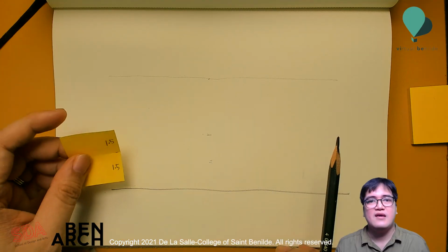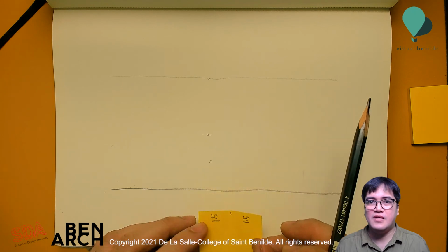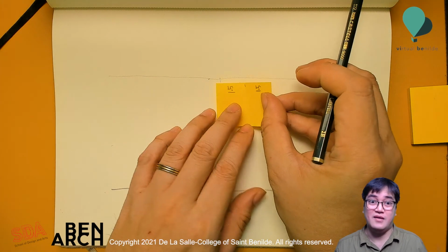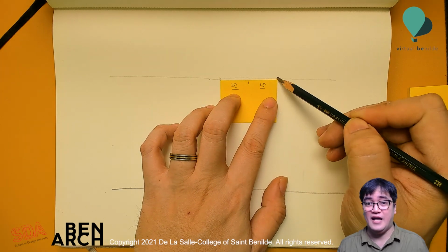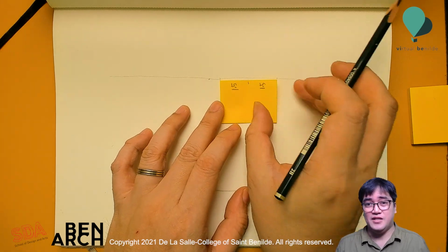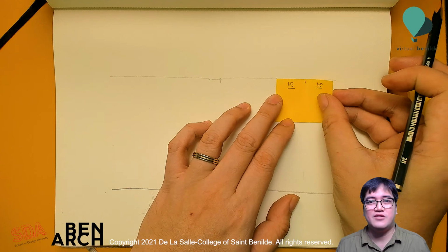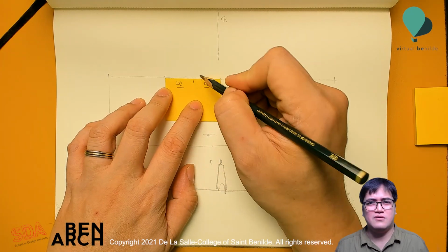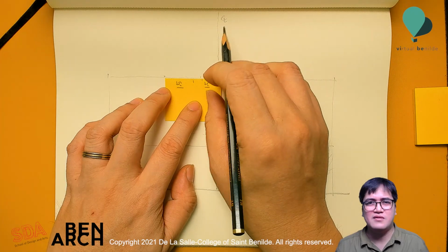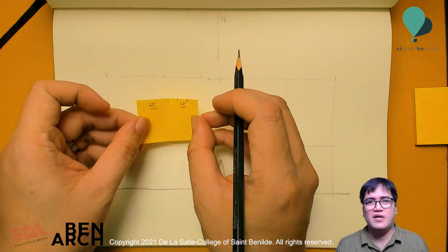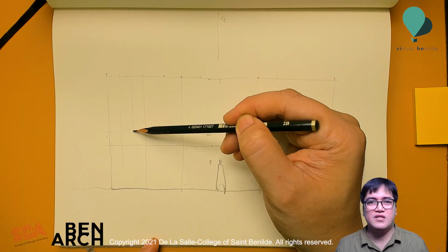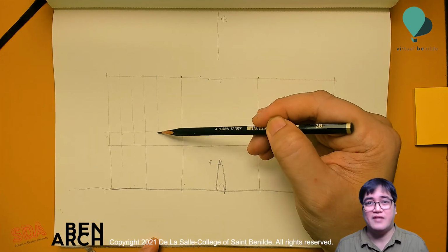And then step 3, with the proportions or dimensions determined being a facade wall measuring 12 meters by 6 meters in height, start light penciling the edges of the building. Start with the general shape. So I am just drawing 2 6 by 6 meters side by side. With the markup image reference, establish the levels, divisions of the walls, and panels.